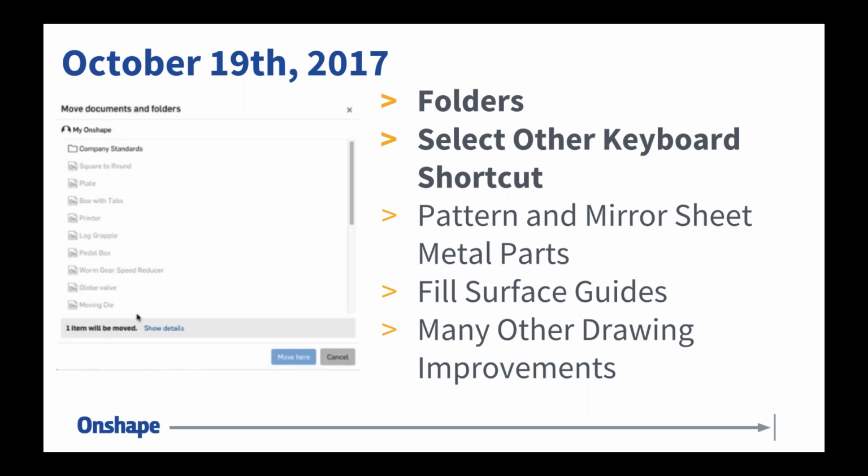Another one that was added with this update is going to be particularly important for those doing surface modeling. You now have an option for guides in the fill surface command. And what's really unique about this is you can specify, I want to follow the guides precisely, or I want a sample. And I'm going to explain what I mean by this in just a bit. But it becomes really critical when you have guides that may not necessarily terminate exactly at the edges of your surface or of your fill. And so, in those scenarios where your curve may not be perfect, but is good enough for the shape that you want, sampling is a good option.